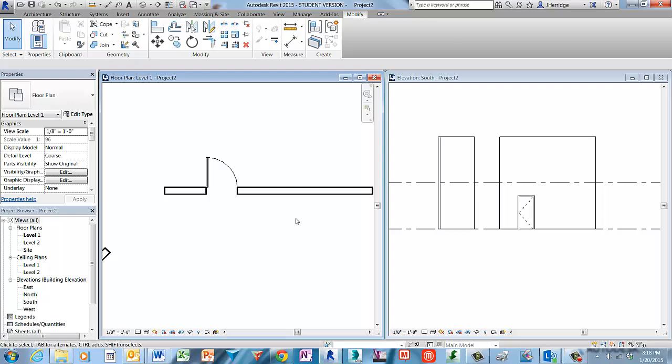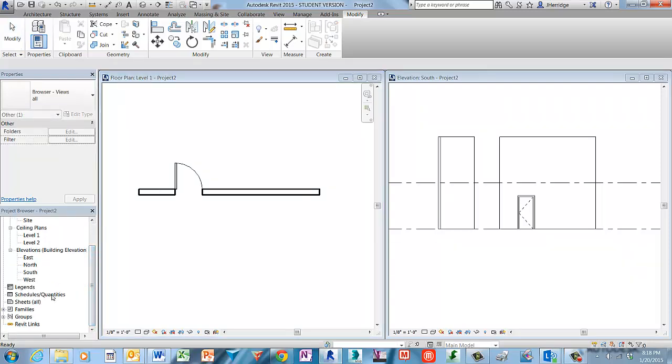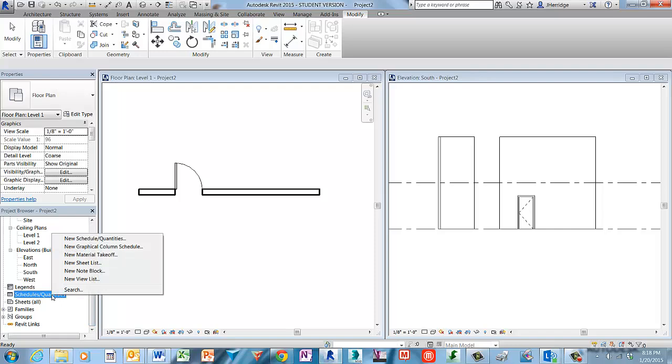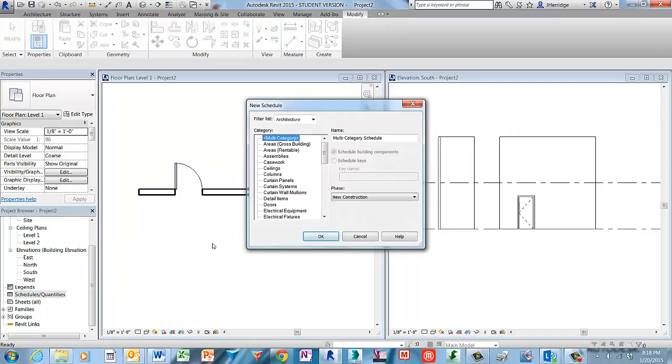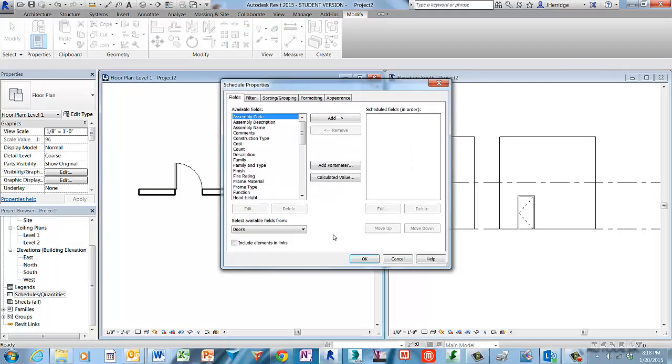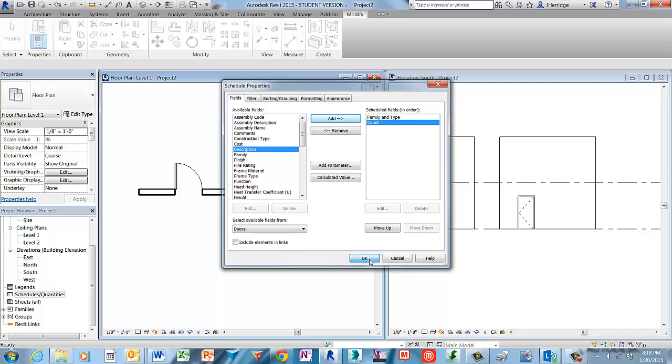Next, to demonstrate the value of building information modeling, I will go ahead and create another view of the model. It just happens to be a schedule view. In this case, I'll create a door count schedule just so that we can see these interdependencies amongst these three views. So I'm calling out the family and type and then adding the count parameter to be displayed in this schedule.